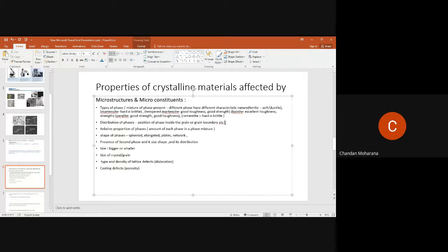No, sir. Never. Pearlite plus proeutectoid cementite. If the carbon weight percentage is 0.8 weight percent, that is called eutectoid steel. If you have a eutectoid steel and you are doing equilibrium cooling from high temperature, you will get only 100% pearlite, right? But if you have a hypereutectoid steel, can you mute yourself? Mute.